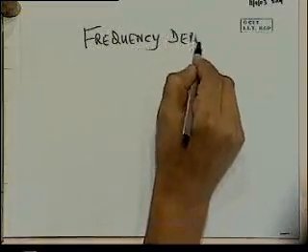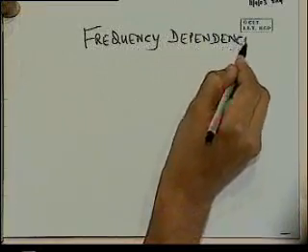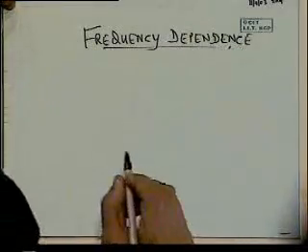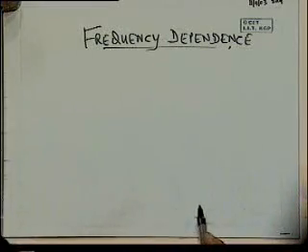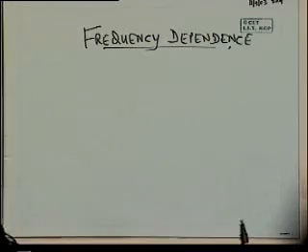And I briefly gave you an overview that, because of the nature, all that we've looked at so far is in terms of DC, static conditions. As soon as you are using AC and start increasing the frequency of the applied voltage, you suddenly start seeing one by one different mechanisms unable to respond at higher and higher frequencies, and so they drop out of the picture. So we'll have to look at it in terms of each polarization mechanism versus frequency: up to what frequency can it sustain, and beyond that it is ineffective.